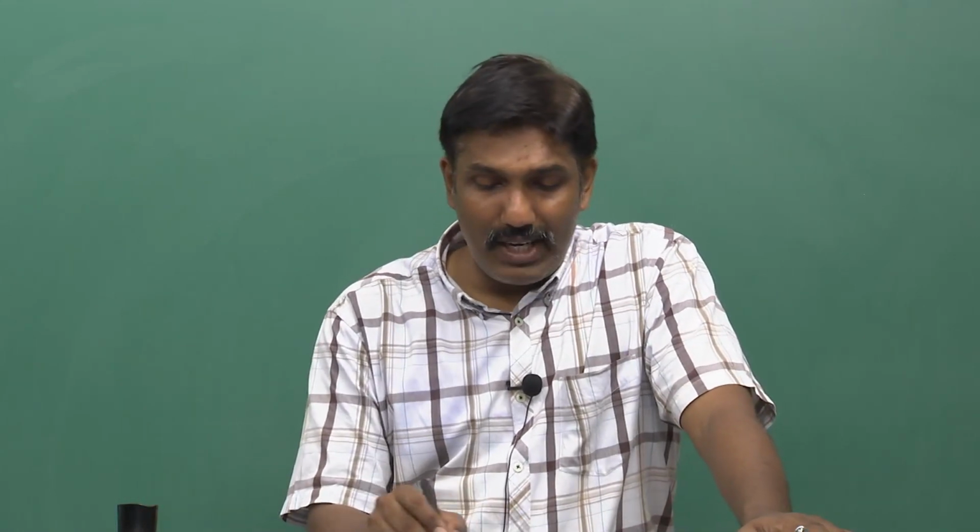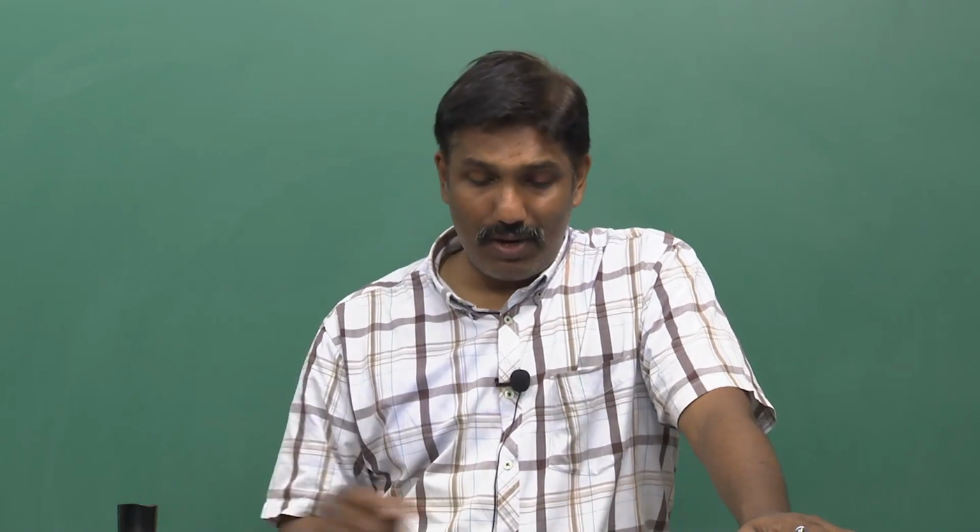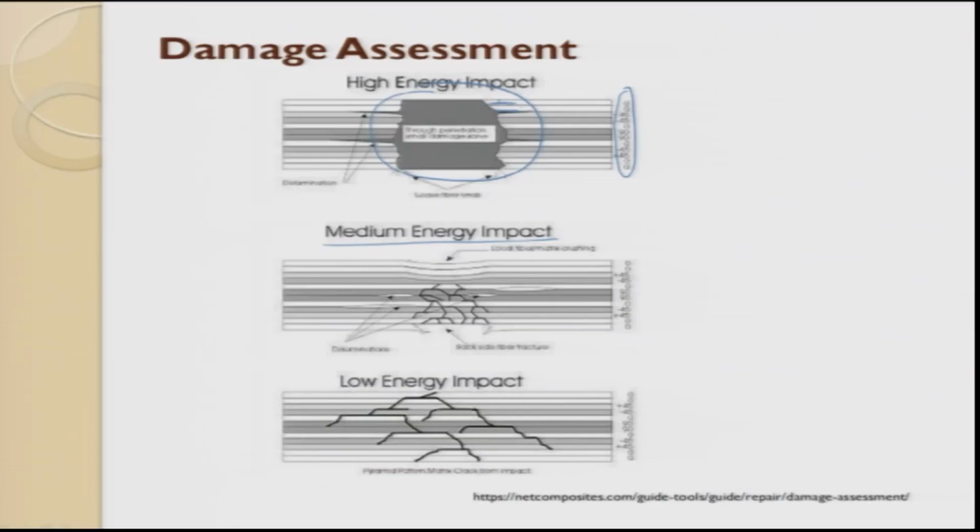If you look at medium energy impact, here what happens is there is a dent which is formed on the top, and the energy has to be dissipated. So, the energy is dissipated as the cracks which are getting formed in between the layers.